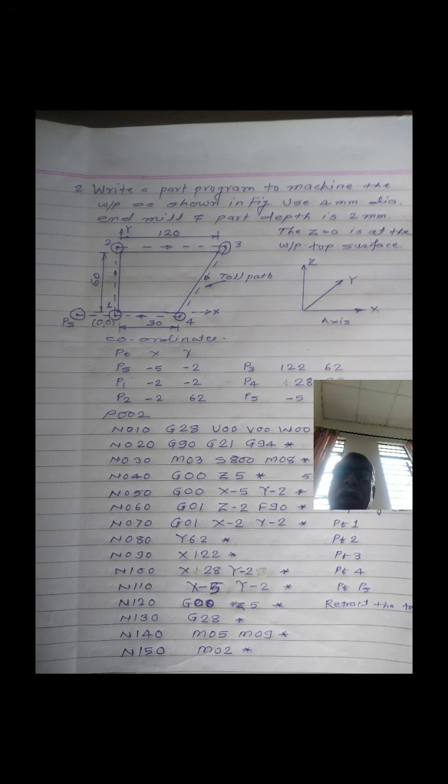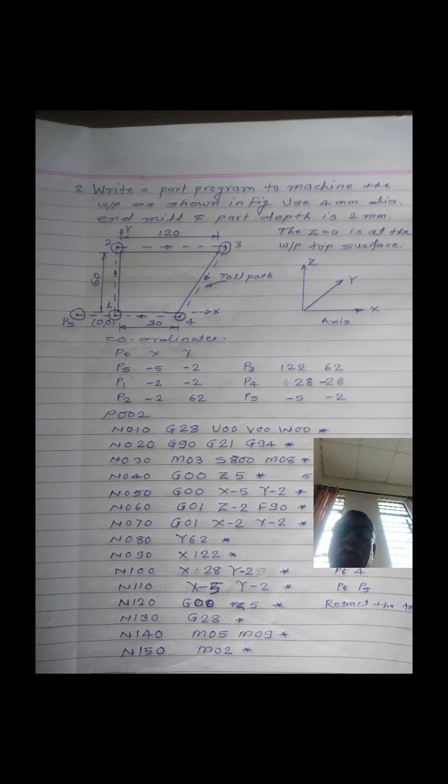Then the coordinates of point 4. Here the cutter moves below the reference point. Therefore, the y coordinate is -2. The x coordinate is 28.